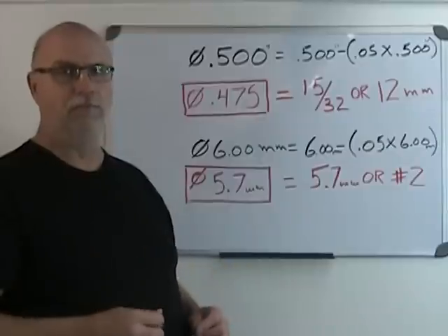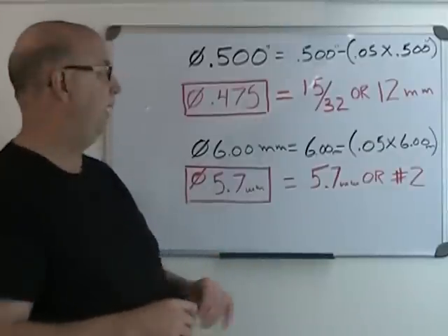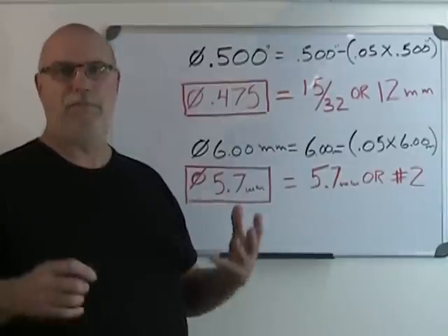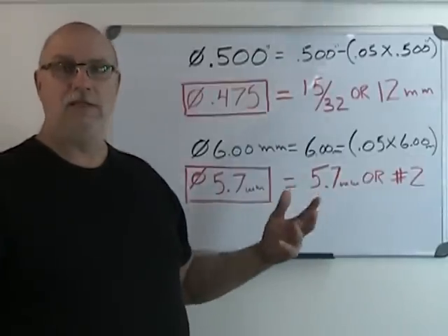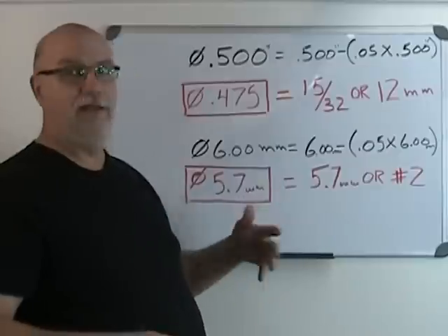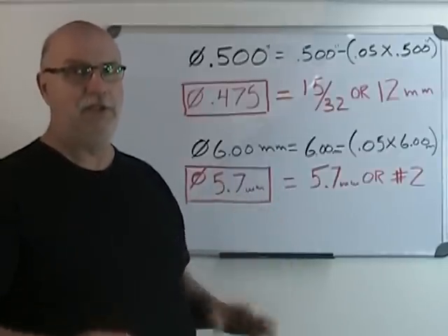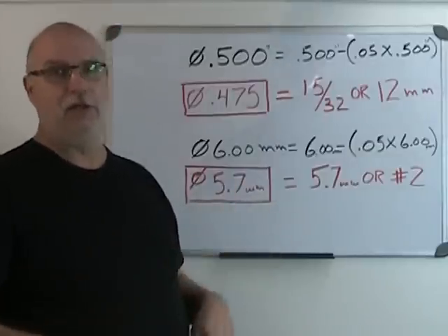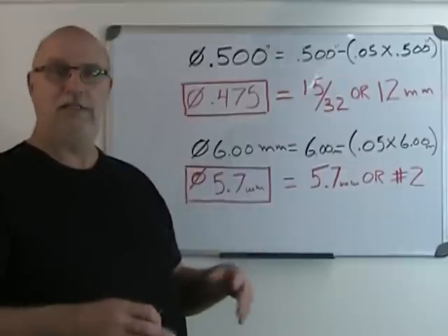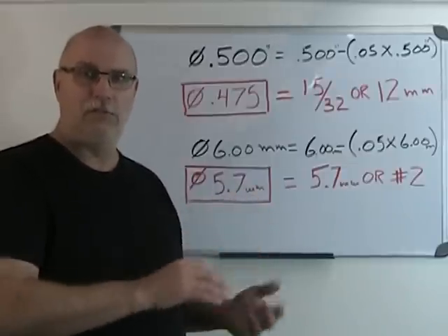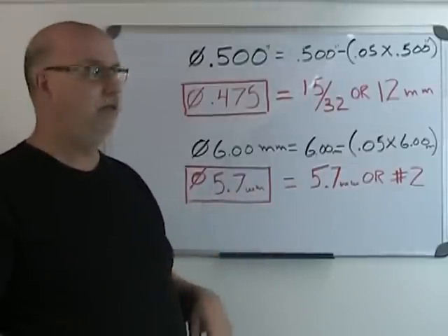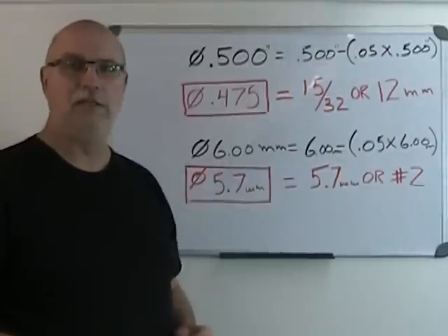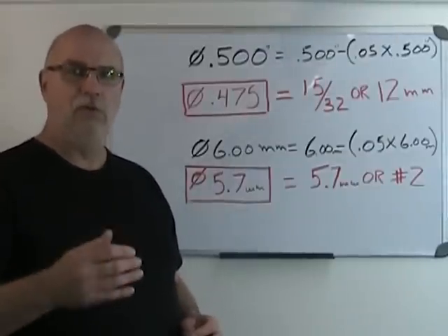You don't want to go larger, especially if you're using a small tap. Now, this isn't how it is described in most books, and that gets me upset. Because the reason that most books apply the old rule, and I'm not even going to state the dimension properly, but it said something like, smaller than a certain dimension, you want to drill a hole a 64th of an inch smaller, and larger than a certain dimension, you want to drill a hole a 32nd of an inch smaller. And that was the basic rule. And the reason why that rule was